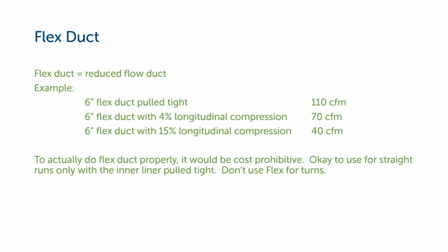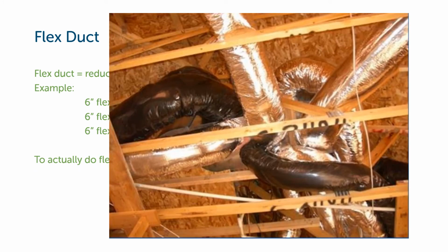So, I think, okay, use it for straight runs with the inner liner pulled out, but maybe don't use flex ducts for turns. And don't use flex duct like this.